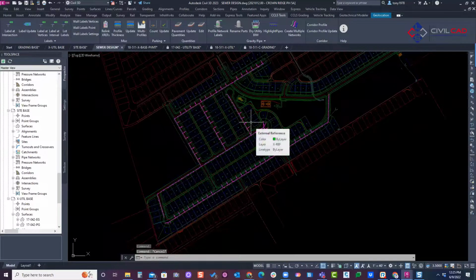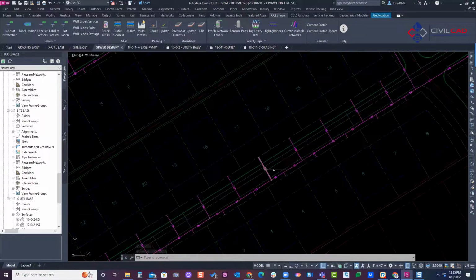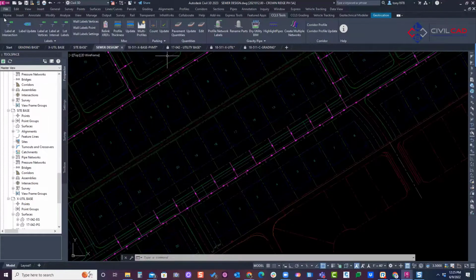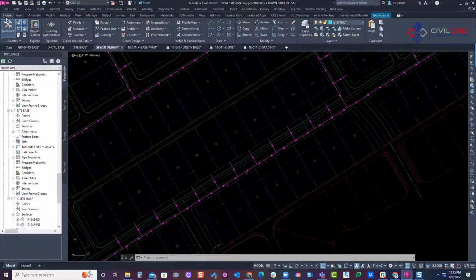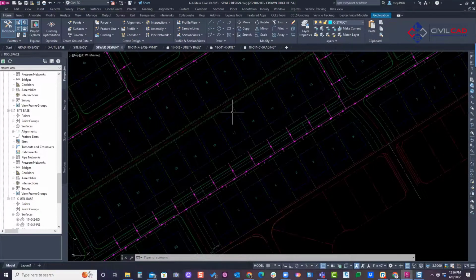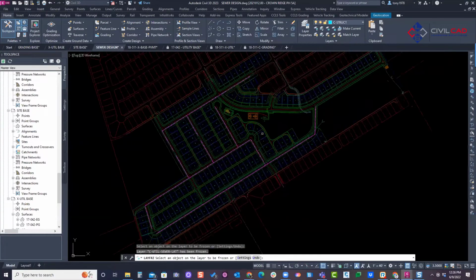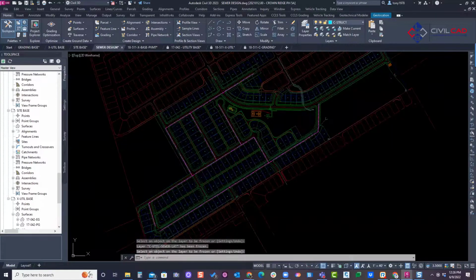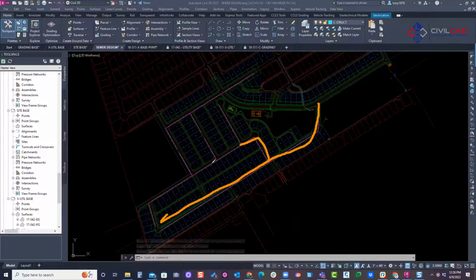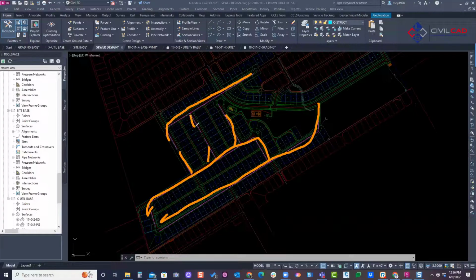So here, for this example, I'm doing the whole sewer design for this subdivision. Now I'm actually going to freeze the laterals. Now you can create the laterals also. But for now, I'm not doing all the laterals. That's a lot of laterals. I'm going to freeze this laterals. Okay. And we have two systems. We have one sewer system, which is this one, and it comes up and goes like this. So this is sewer 1 network. And then this is sewer 2 pipe network.